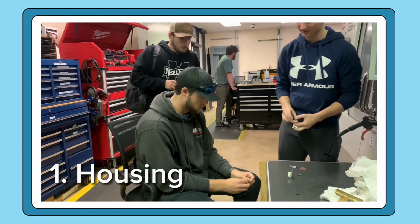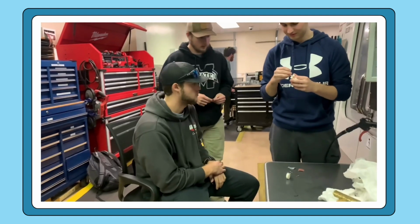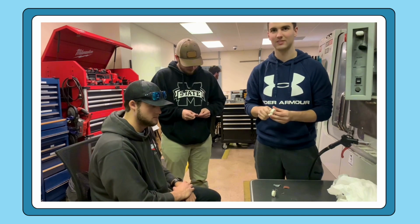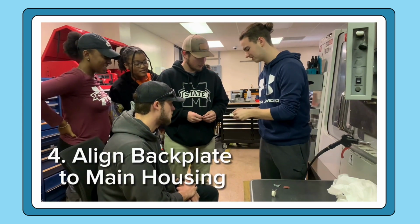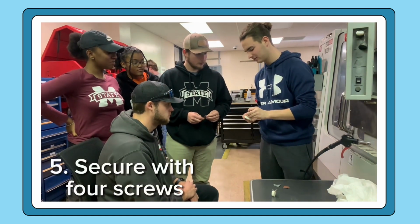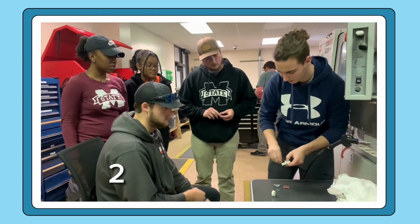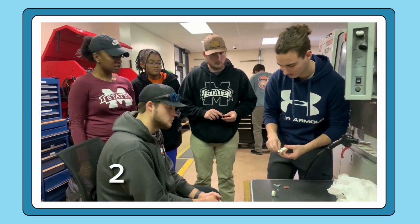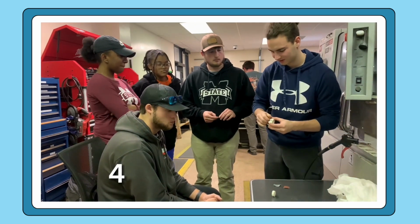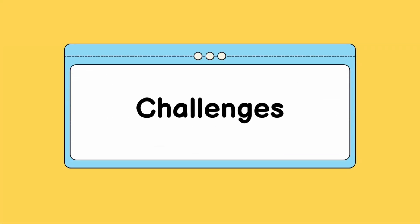First, the housing, then put the eccentric shaft into the rotor, put the eccentric shaft and the rotor into the housing, align the back plate of the housing to the main housing piece. Secure the back plate to the housing with 4 screws. Lastly, move the rotor around to make sure that it spins freely.